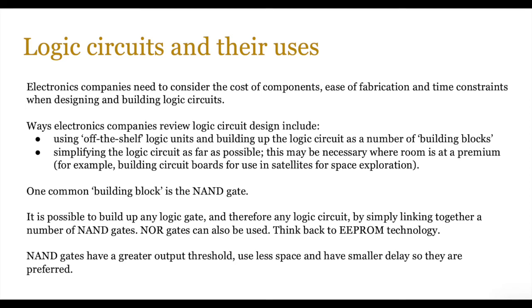Now one common building block is the NAND gate. So it's possible to build up any logic circuit using a NAND gate, and therefore logic circuits are often simplified by just using NAND gates. NOR gates are also used, and think back to when we were talking about EEPROM technology, electronically erasable programmable read-only memory, NOR gates were used there. So NAND gates are cheaper, used in SSDs, and NOR can also be used, but a bit faster, so these are used in EEPROM chips.